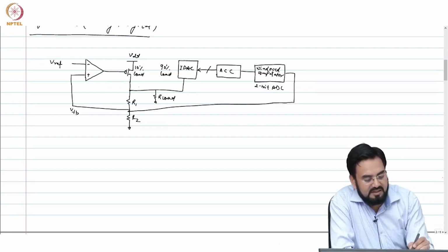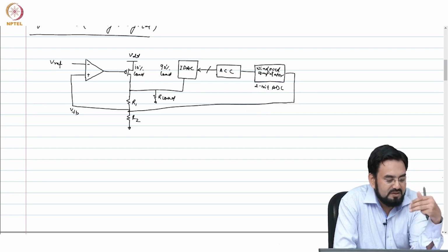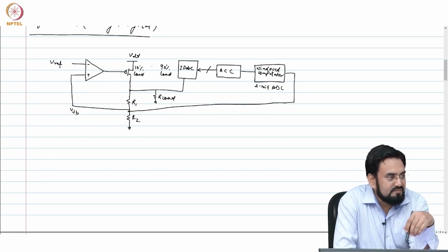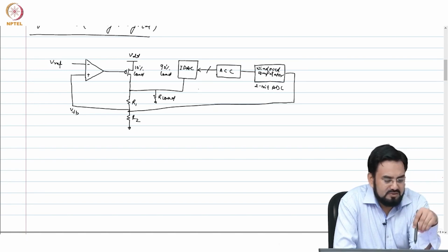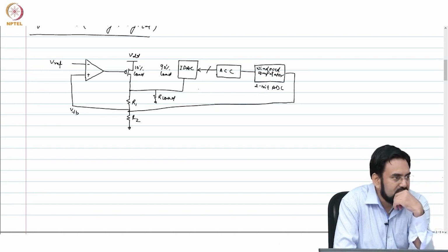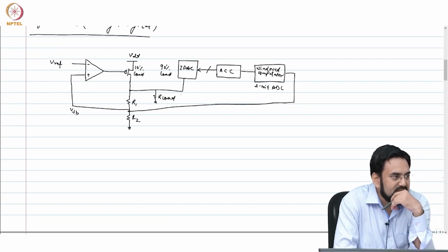So, you can sense this analog current and you know this analog cannot take more than 1 milliamp, that is what you have designed for. So, whenever current goes above 1 milliamp, you just activate your DAC, okay. So, you keep increasing that. So, what will happen, this current will start reducing. So, let us say the LSB you have turned on, okay. So, it goes let us say 1.1 milliamp or so. So, depending on the resolution it will turn on that many IDACs which will carry 100 microamp of that extra current. So, this will remain at 1 milliamp, okay.